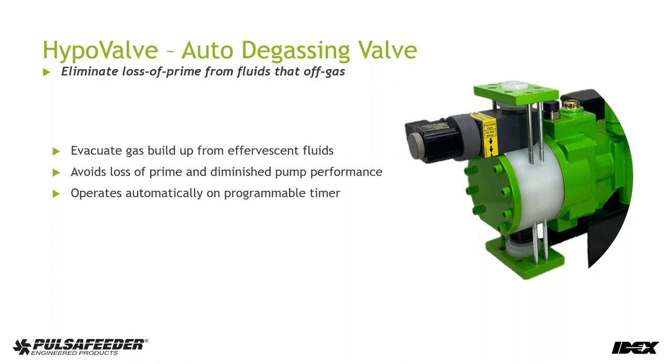This also is a feature for when your pump is primarily used for fluids that can off gas, in particular sodium hypochlorite. At room temperature, it vaporizes, it builds up gas inside the system lines, and in particular the pumps here. And we get into that situation where we don't have those solid hydraulics because there's gas in the line.